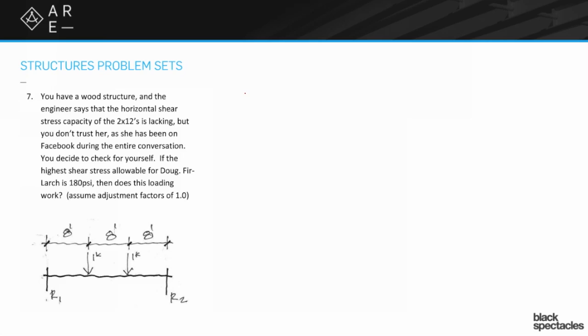And so we have a beam here. It's intriguingly symmetrically loaded. I love it. So tell me about it. Okay, so we need to think about what is the shear through this beam. So the maximum shear through a beam like this is going to be at its end span. So by seeing that it's symmetric, I'm just going to use my judgment and say that it has 1 kip of reaction at each end of the beam. And from there, that's our shear.